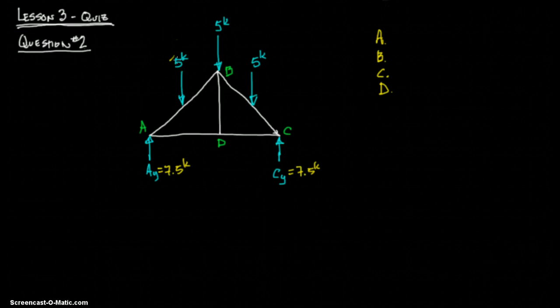We know that these two loads right here, or these external loads, are not being loaded at a pin, or at a panel point, as you might want to call it. So these are all pins. That's another thing we know. And so these two are not being loaded at a pin, so that's going to induce moment into these connections right here, and we'd have to design for that. Another thing we know is that this is a zero force member.